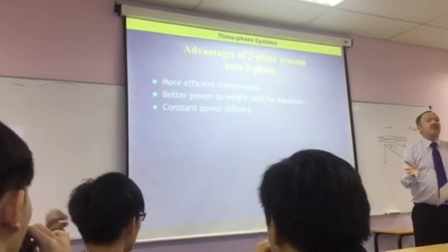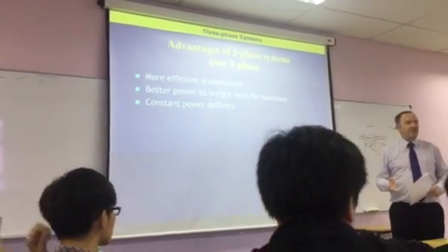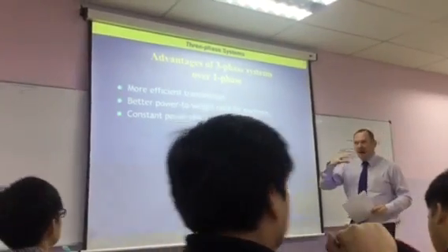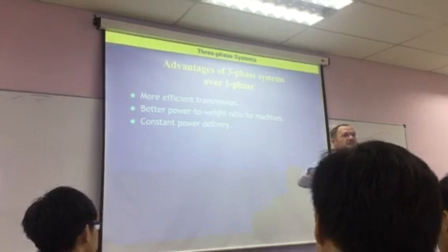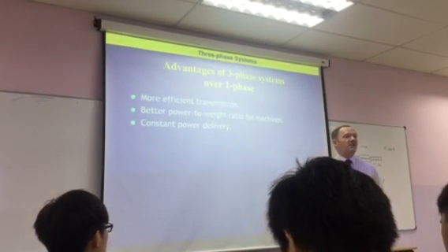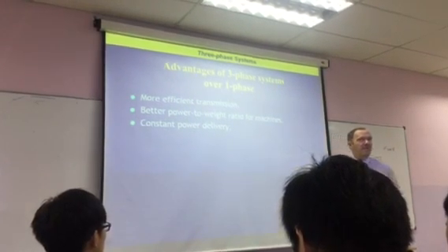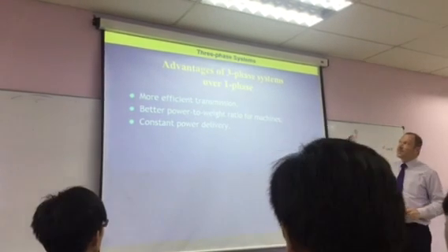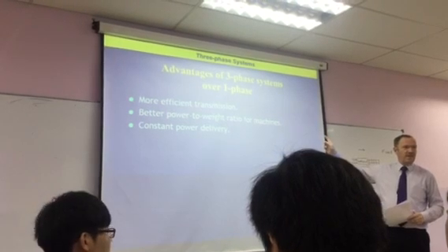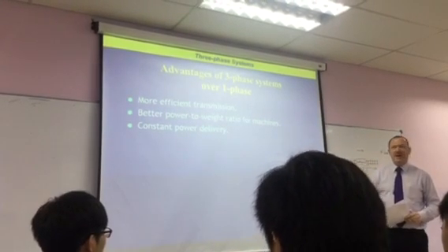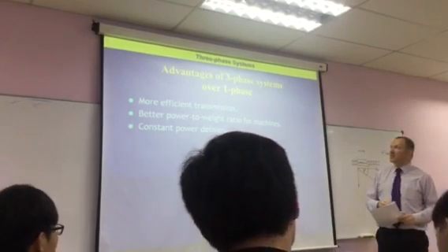You'll get three-phase coming into this building, where it will be divided up into single phase. So at home, if you live in an apartment block or on a street, it will tend to be split at a substation into single phases. But for transmission over longer distances, we tend to use three-phase systems. So that's actually combining three phases into one transmission.